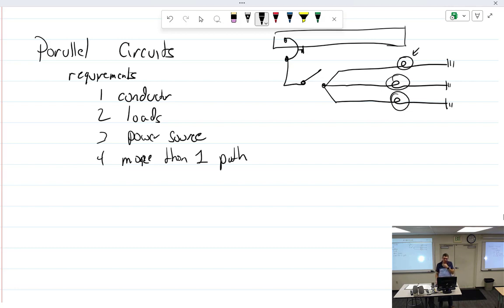So, all right, what if all three of them are dim? Unusually dim. Bad switch. Yeah, you might have a bad switch. And so I say, all right, I might have a bad switch. Well, what does it mean bad? I mean, the lights go on, the lights go off. Maybe the connecting point is corroded, so it's not making a full connection.